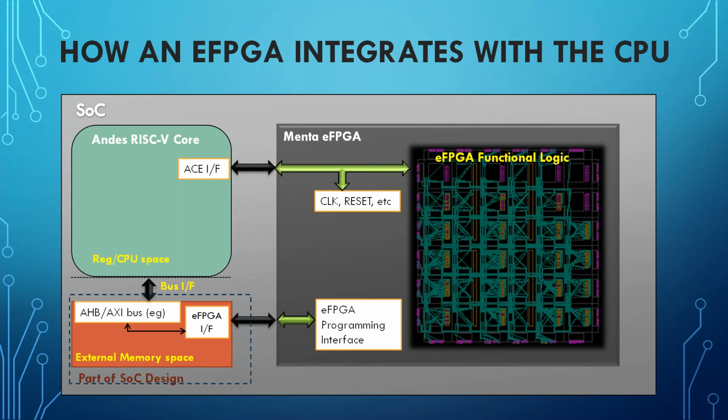Okay, so how does it integrate with the CPU? At the SoC level, we have the CPU with the ACE interface connecting to the Menta eFPGA. That'll have clock and reset and the instruction, source and destination registers, and some other I/O signals for control of data flow.